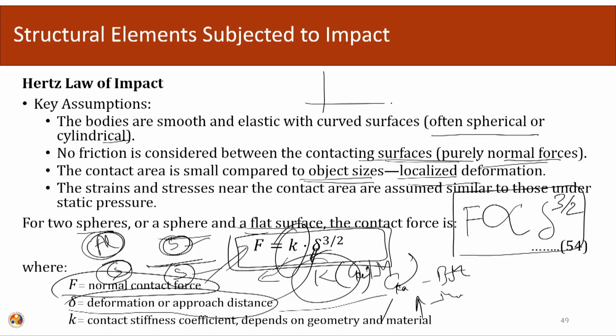Okay. So, if you look into the Hertz law for the purely elastic impact, it will give a proper bell curve. Depending upon how the elastic behavior is affected, the other iterations can be used to evaluate the contact force relationship. Hertz law primarily gives the evolution of the contact force when two bodies are in contact. So, this is a powerful law to calculate the contact forces.